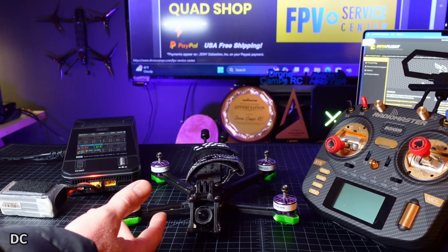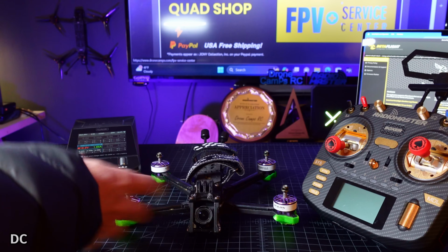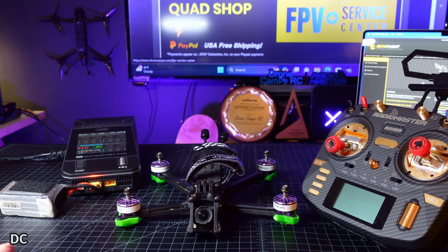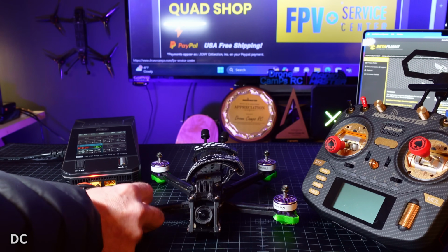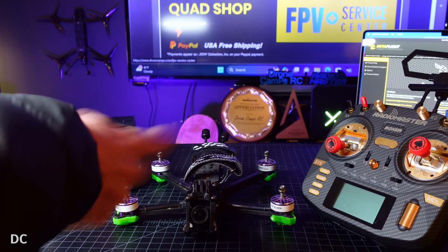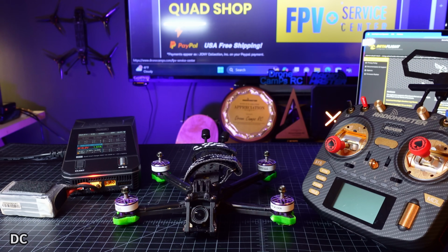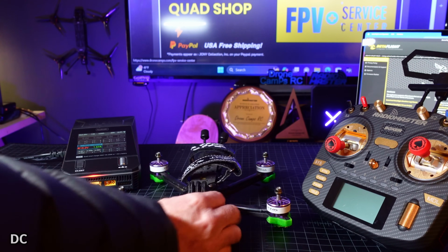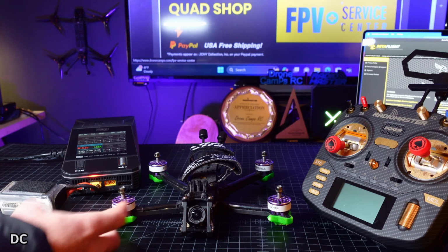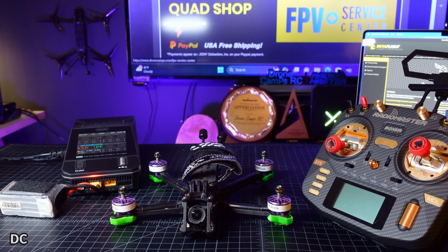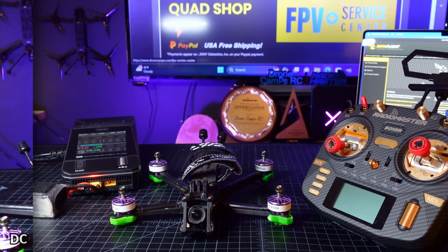And then the quad also utilizes that mechanical wrong thrust, and it initiates a roll. So that's what happens. We have overcompensation from the flight controller and physical reaction from the motor as well. Those 2 combinations are pretty deadly. So you want to be careful there for your maiden flight to make sure that everything is flown line of sight first before you goggle up.